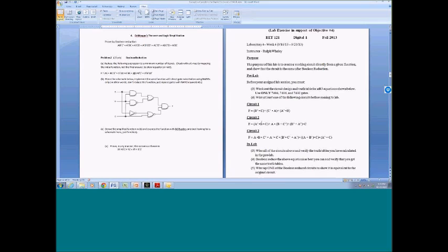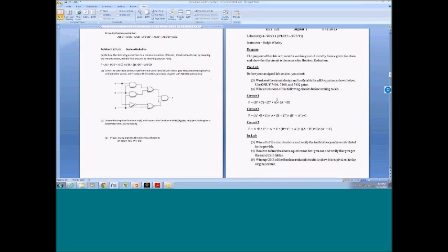This is circuit 3, but this last one is a lot of wiring. It's a very complicated thing, and I think it reduces down to A or C, and this one's like A, B, or C, something like this. Then they look at it and they're like, oh, it's just this. Okay, fine. But this is where it's really motivating. I tell them you can only use the 7404s, 8s, and 32s. Those are all 2-input gates, so they can't use 3-input gates, and they've got to think about it. So this is a nice exercise.